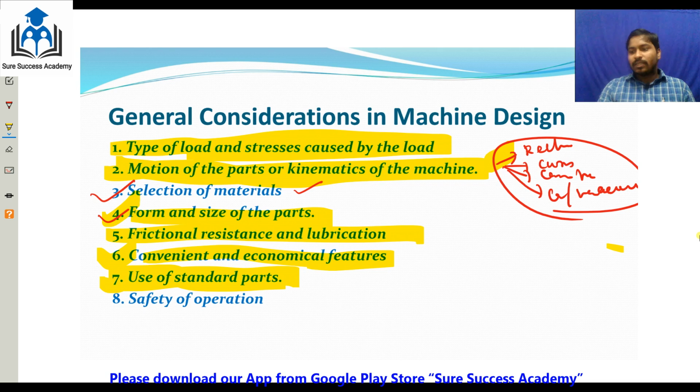And you have to always see the standard parts. The parts of the elements should be standard parts. The use of standard parts is closely related to cost, because the cost of a standard or stock part is only a fraction of the cost of a similar part to be ordered. Standard or stock parts should be used whenever possible, such as gears, pulleys and bearings, and parts which are available in regular stock, like screws, nuts and pins. It means you have to use standard parts. If available in the market, the pulley, key, these are all standard sizes. You use them, so you can save the cost.